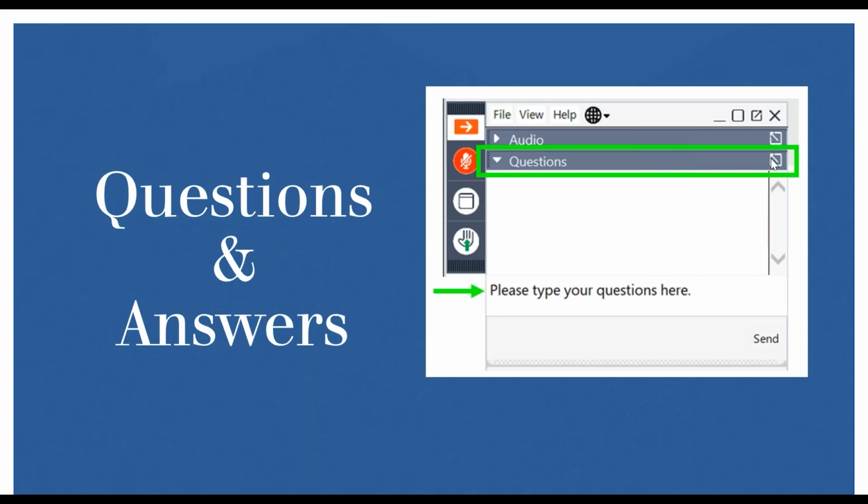For the tubes, whether they are expensive or not, I'm not too sure how to answer that. But for the Dräger tubes, one of the reasons why tubes are still commonly used in this area is the selectivity aspect. Tubes can be used to measure all types of gases, and in some cases where there is cross sensitivity that the gas detectors may not be able to handle, because the sensors in the gas detectors may have cross sensitivity to the measured substances, you can use a tube to do spot measurements. Okay, thank you, Agus.